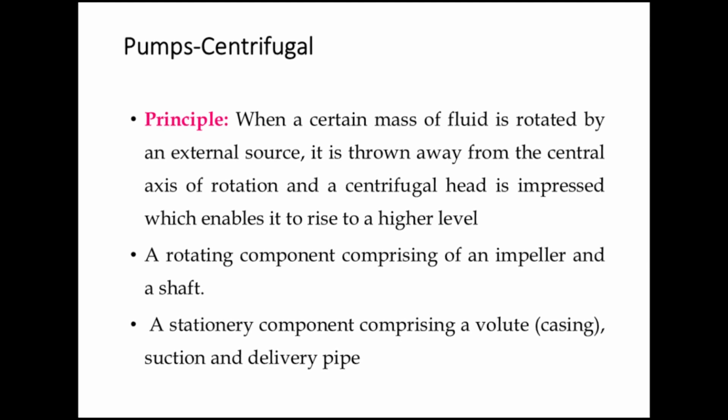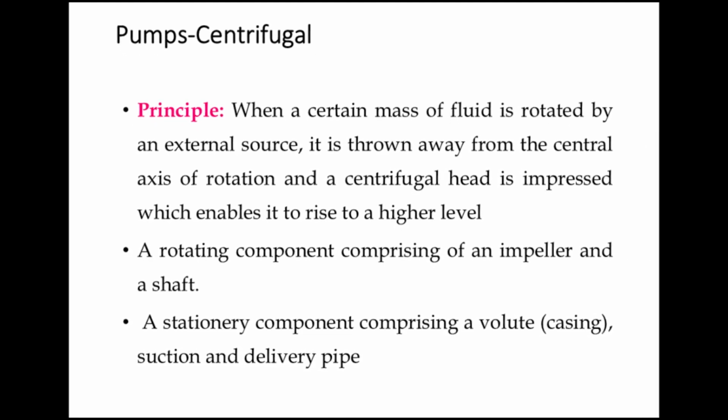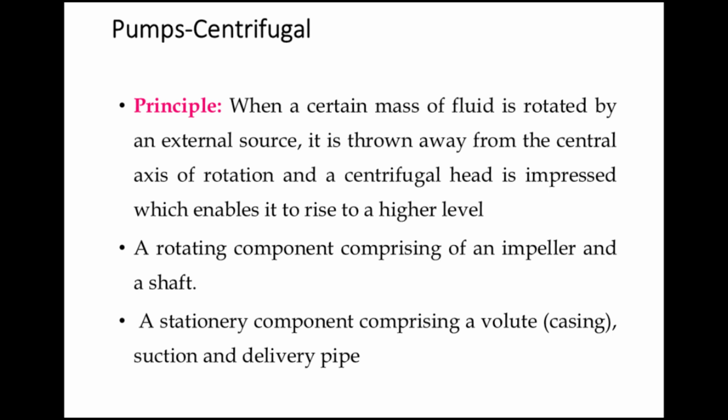Centrifugal pump principle. When a certain mass of fluid is rotated by an external source, it is thrown away from the central axis of rotation and a centrifugal head is impressed, which enables it to rise to a higher level. A rotating component comprising an impeller and a shaft. A stationary component comprising a volute, suction and delivery pipe.